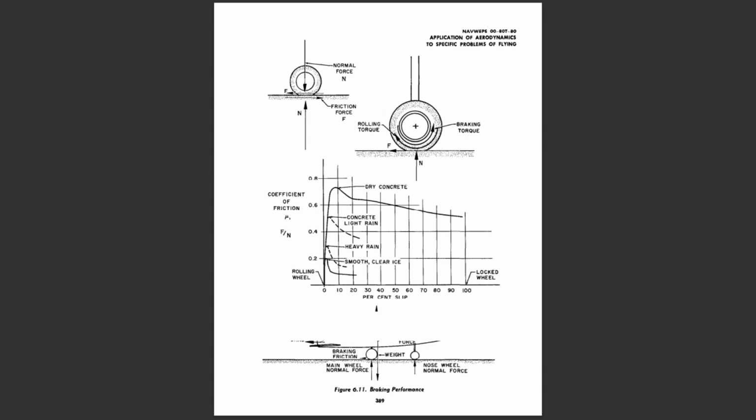After touchdown, the pilot lowers the nose until the nose wheel contacts the runway. Then, the pilot applies the brakes while easing the stick back without lifting the nose wheel back off the runway. The effect is to minimize the normal force on the nose wheel and increase the normal force on the braking surfaces. While the principal effect is to transfer normal force to the main wheels, there may be a significant increase in normal force due to a reduction in net lift, i.e., tail download is noticeable. This reduction in net lift tends to be particular to tailless or short-coupled airplane configurations.